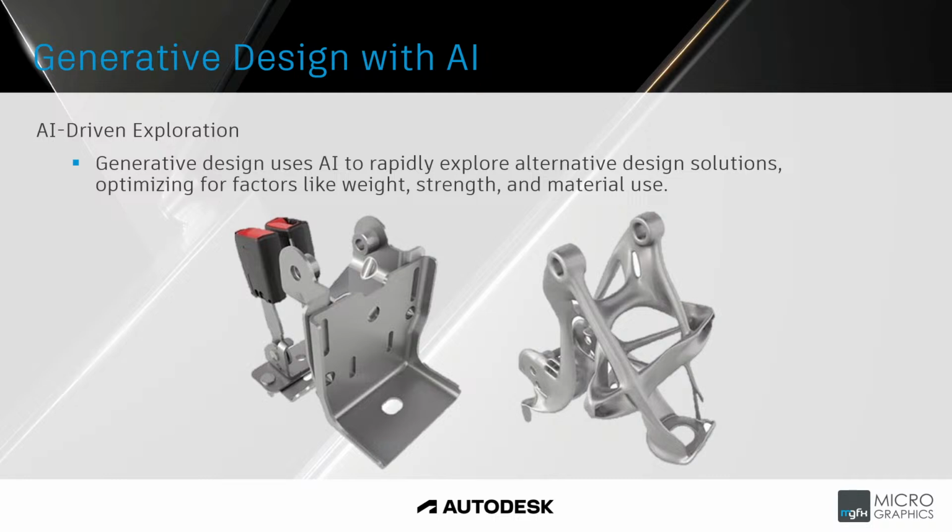The bracket on the left-hand side is for mounting into the vehicle and attaching the seatbelt buckles to. And it's made up of 8 or more components, all pressed steel that have to be pressed individually and then welded or fused together. So there's quite a large production chain, value chain added to that. There's all the assembly process and the welding.